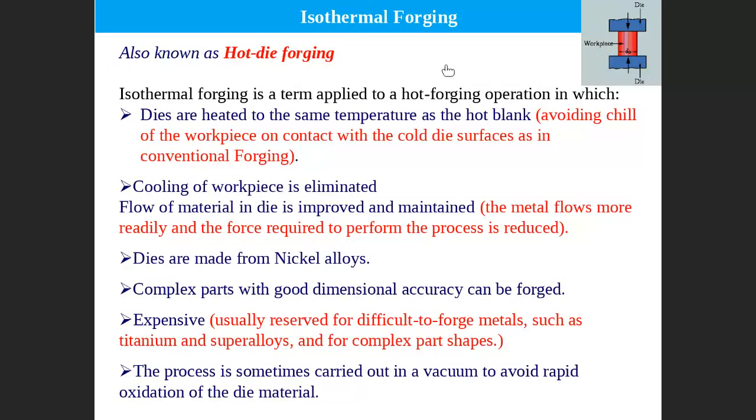We said that the problem comes when you do upsetting in hot die forging, when the workpiece is hot and the die is cold. Whenever the cold die touches the hot workpiece, the upper and lower edges cool down compared with the core. So in the middle, this will deform laterally more, and there is less deformation at the edges.